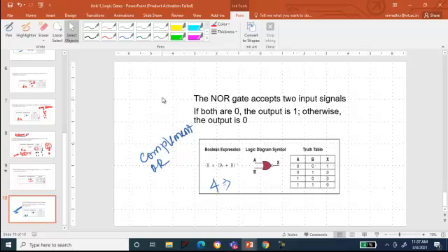And finally the NOR gate is nothing but the complement of the OR gate. And again draw the OR gate, A, B as the input, and at the output of the OR gate you put a bubble, that is said to be an inverter. So you will be having A, B input, 4 possible combinations here. So other than the first one, the rest all is 0. This is X is equal to A plus B, the whole bar.